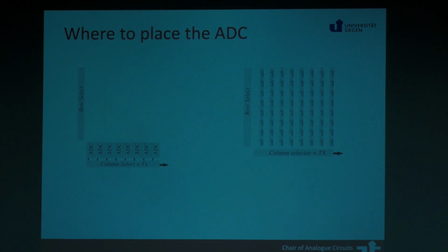So 0.3 second of imaging. What's the time required to integrate our camera pixel? We're giving 50 milliseconds. Remember yesterday we said 1 millisecond of reset and 49 millisecond of integration. That's still smaller than 0.3 seconds. So you need a fast camera, but not a terribly fast camera either.